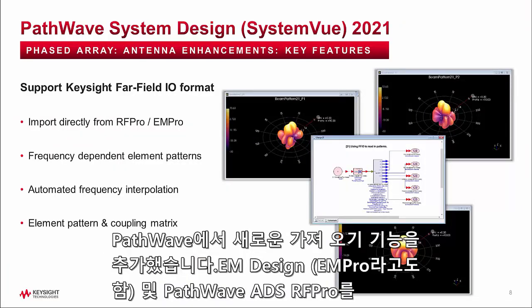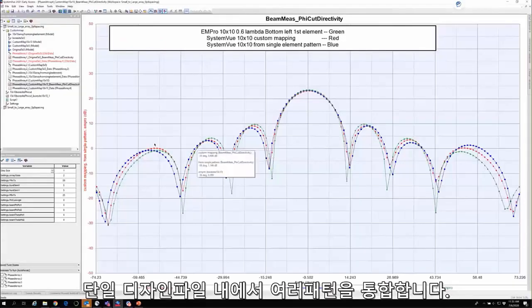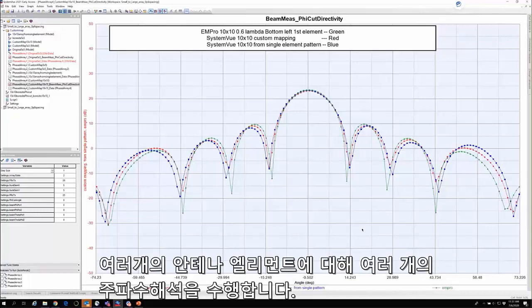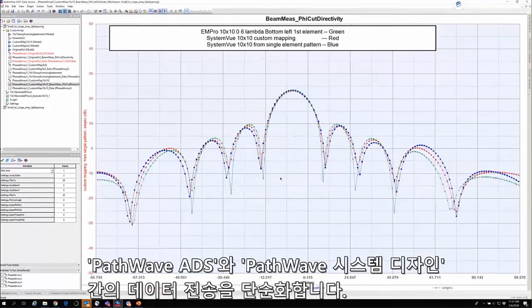We have added a new import feature from PathWave EM Design, also known as EM Pro, and PathWave ADS RF Pro. This is called Far Field I/O. Within a single file, it incorporates the patterns of multiple antenna elements, and for each element, it includes the patterns for multiple frequencies. This streamlines antenna pattern imports and simplifies the transfer of data between PathWave ADS and PathWave System Design.